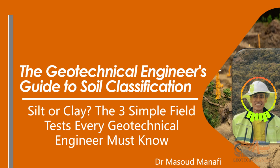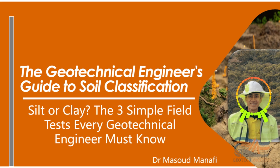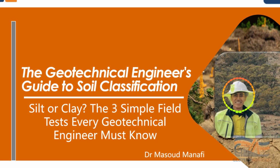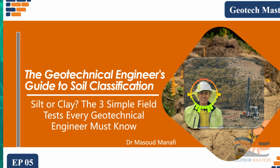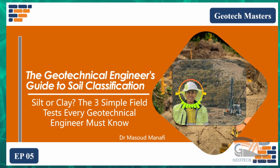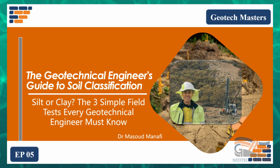There are three on-field tests available: dry strength, dilatancy, and toughness. These are your essential toolkit for fine-grained soils. They are described in both the ASTM D2488 and AS 1726 standards, which shows how universal they are. Mastering these skills is a critical step in your journey. Let's get our hands dirty and learn how to do it.